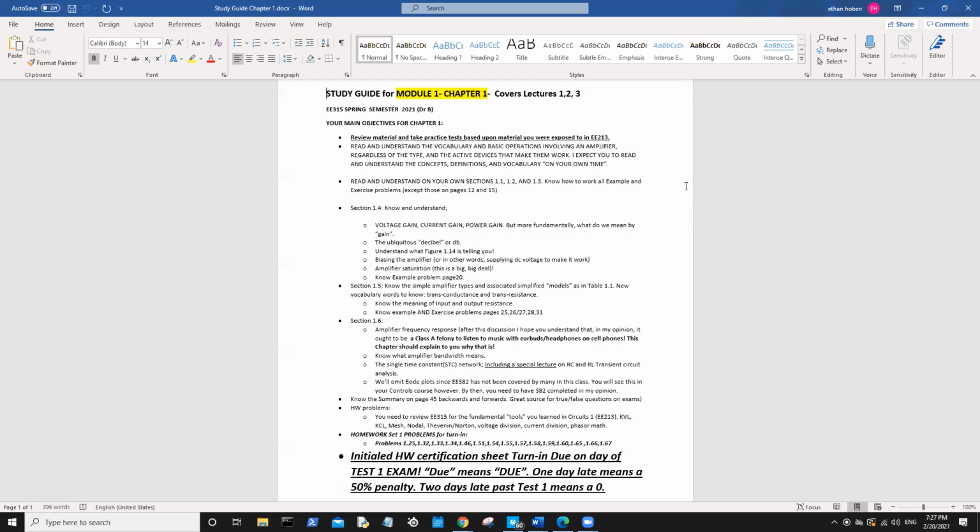No, example problem on page 20. Does anyone know what that's referring to? Yeah. So that's where you need to know that if you're given peak voltage or peak amperage, you find your actual RMS voltage and current that are usable in the equations, and then after that it's basically just finding the gains and then doing a power balance.